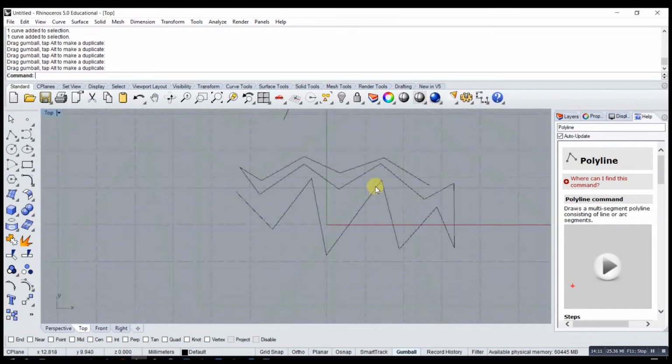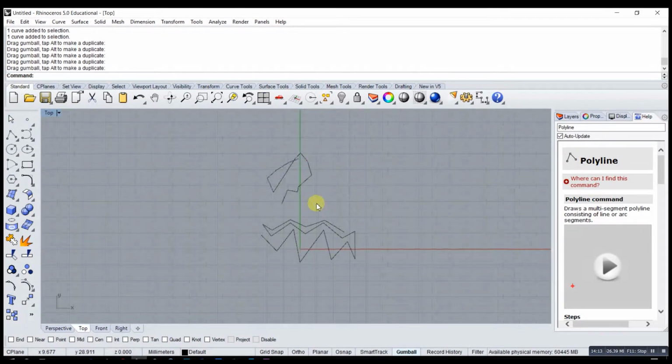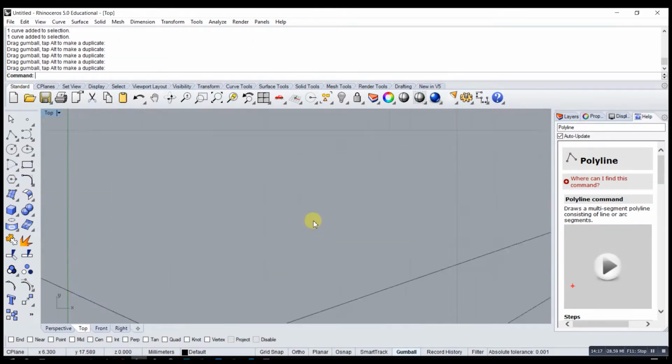We'll go back to our top view, I guess, and we'll just take a look here. So I've got a pretty good selection of line work here, and let's pretend by accident I zoom way in. Maybe I zoom way too far in and I lose my workspace. Where's the things I drew? You start freaking out a little bit. There's one navigation tool to save you in that situation, and it's called Zoom Extents.